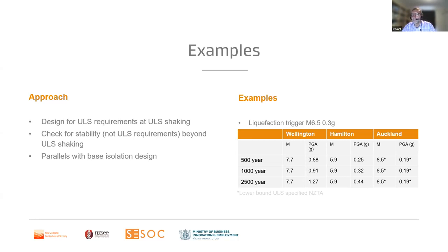But if liquefaction needs to be considered, then to provide stability it would be considered necessary to pile, at substantial additional cost, with those piles extending down to greater than 15 meters depth. So for that situation, let's see how we would respond with different levels of intensity of shaking. So first of all, the Wellington site.